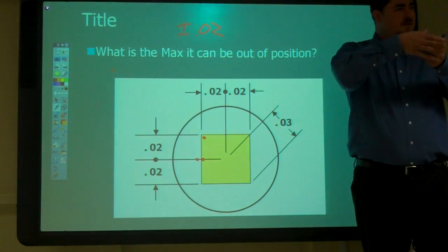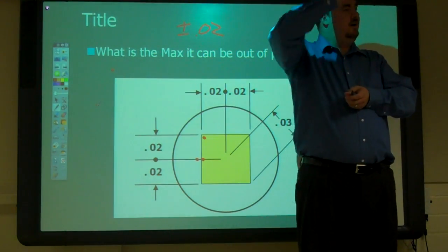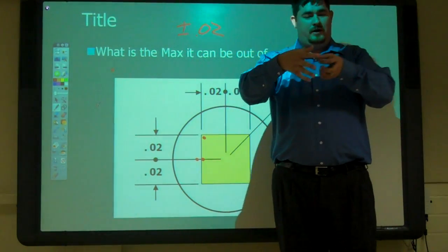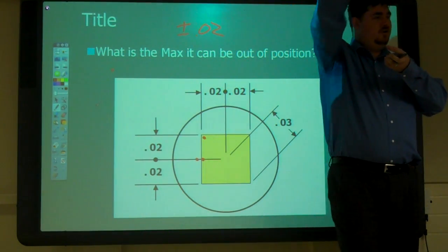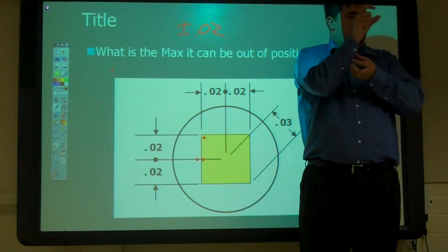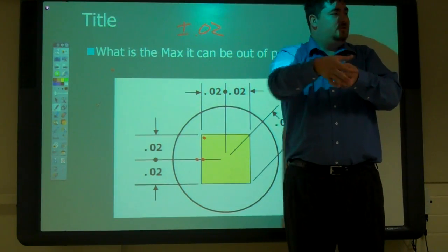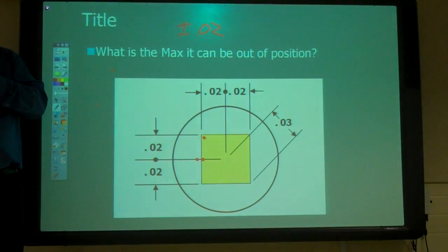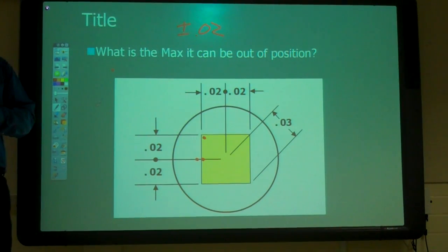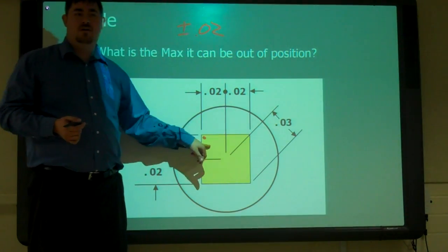If we have two holes and they're lining up with each other, we have our clearance in there, right? And that's set up so the hole can move around and the pin or whatever that goes in can always fit in, with a certain amount of clearance. So it doesn't matter if it's that way or sideways. It has the same amount of movement in all directions. So then wouldn't it be smarter, instead of doing the square zone, to do a circle, a radius?